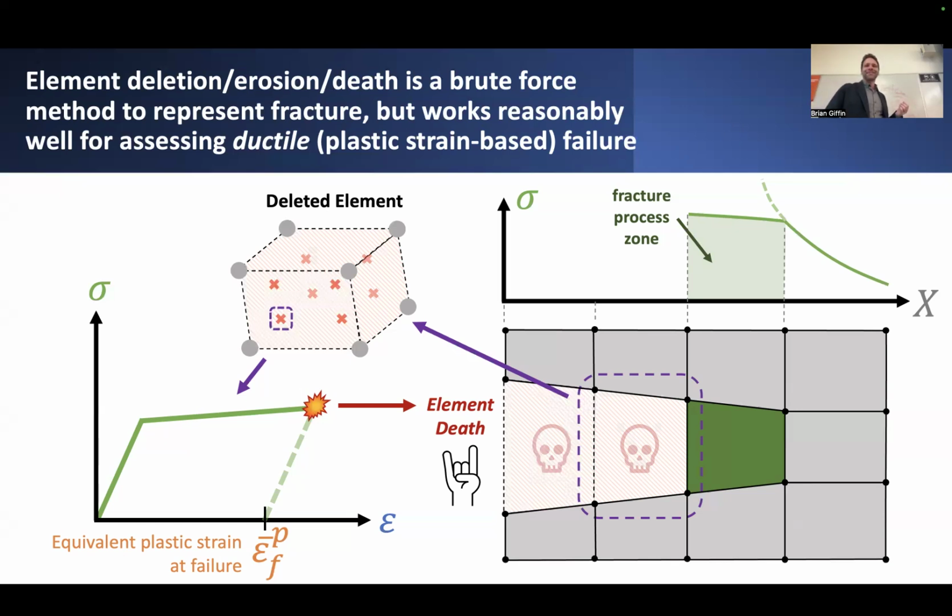So just be cautious if you're using element deletion. There are other reasons why element deletion can help you. Obviously, if the elements are really getting distorted or becoming a problem in your analysis, there are occasions where it's actually useful to just delete them just to make sure that they don't become a huge problem. But otherwise, it's also kind of a method of last resort if you're trying to model things like fracture. But it works okay, at least if you're doing ductile fracture.